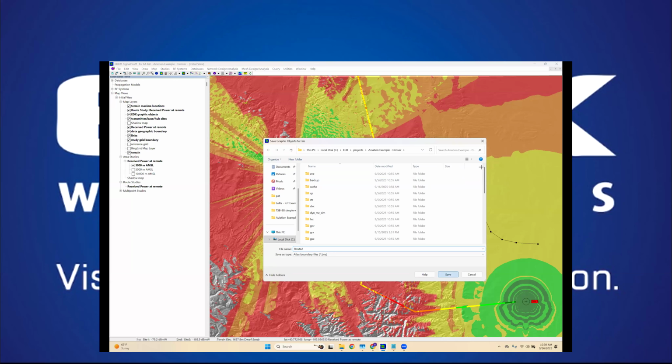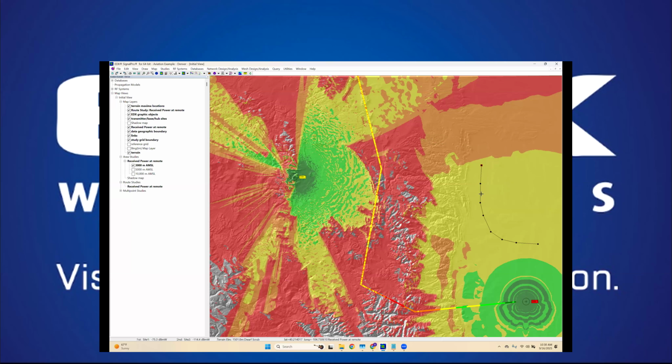Now at the moment, this route doesn't have any elevations in it. It's just those locations. If I pop that open in, again, the spreadsheet editor of your choice, just open it as a CSV, you can access those elevations and plug in elevations for each of your waypoints. And then once you've got that file, what you do is add a .lev extension onto the end of it, so that you have a file that's called, for example, route.bna, and then route.bna.lev.